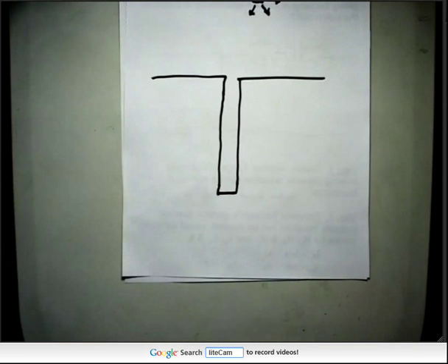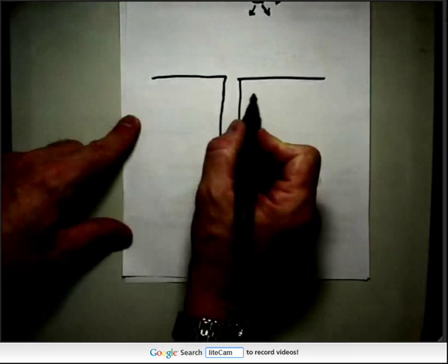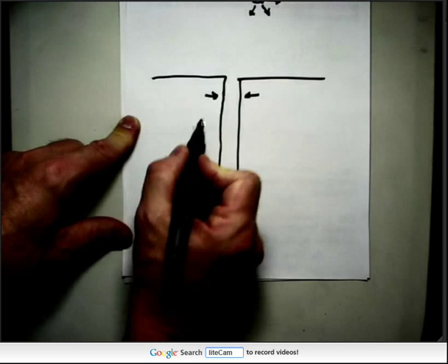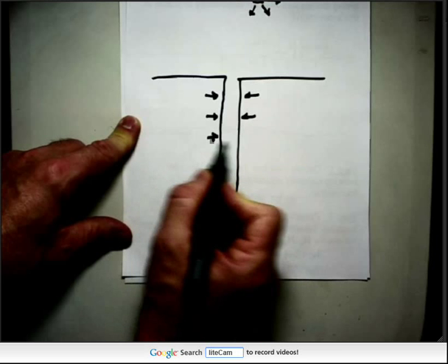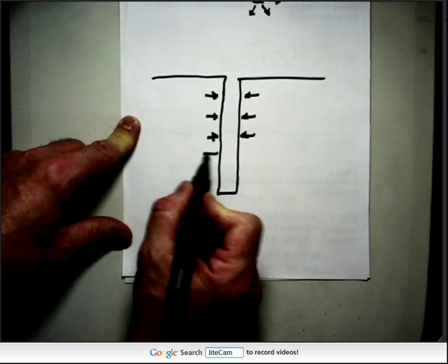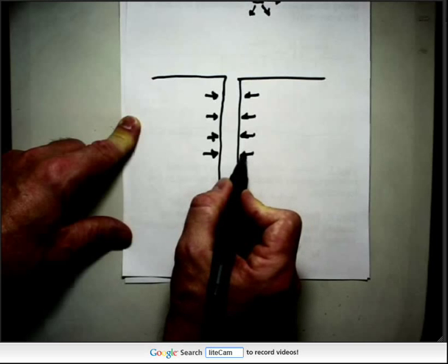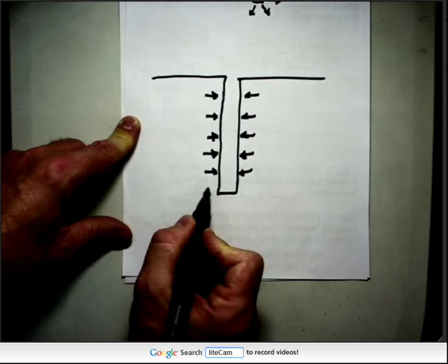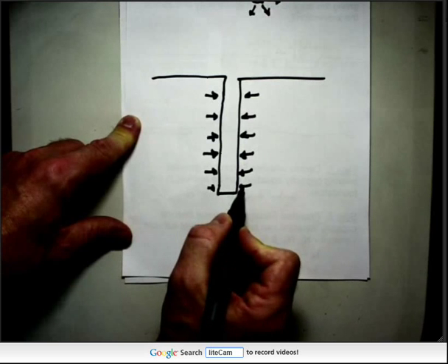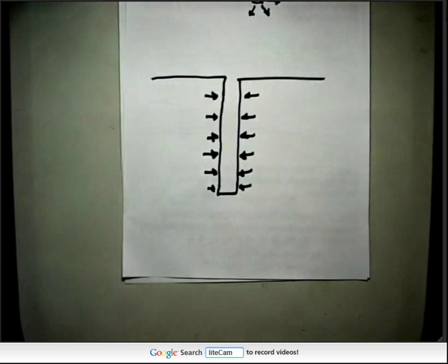And that, unfortunately, allows the soil to relax inwards slightly. We might, in various pile techniques, try and support the sides of that hole so we can reduce the amount of relaxation, but it's very hard to prevent all relaxation. So there's two things about bored piles.